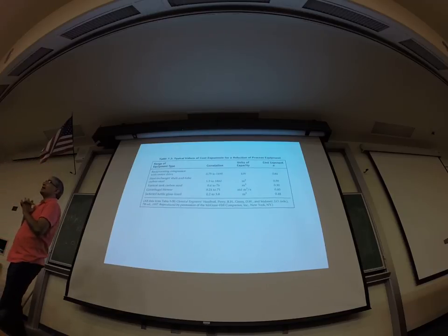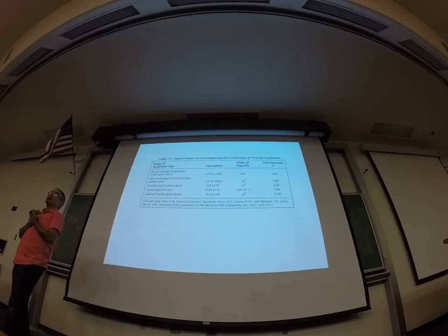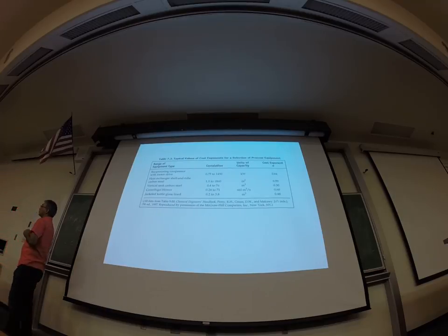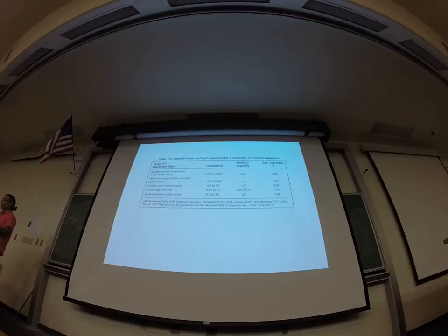If you do all the estimates, you can certainly do this yourself. If you do a process flow diagram and make an estimate based on it, you can see how much that estimate differs from the one you could have gotten from the block flow diagram using just the 0.6 factor.